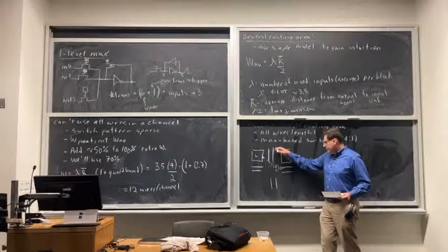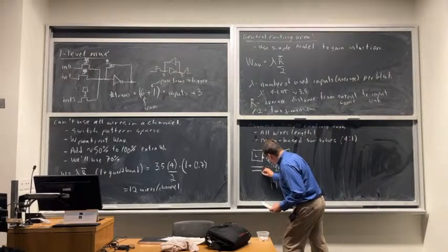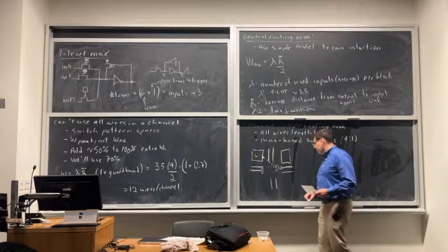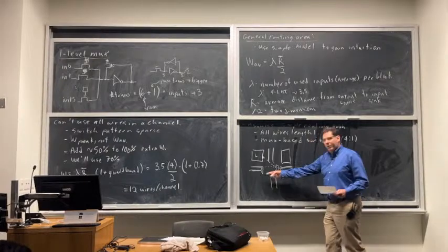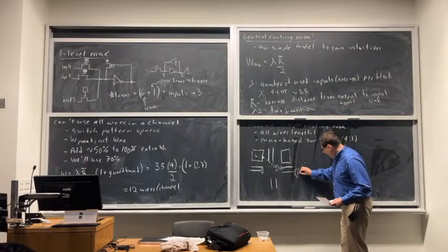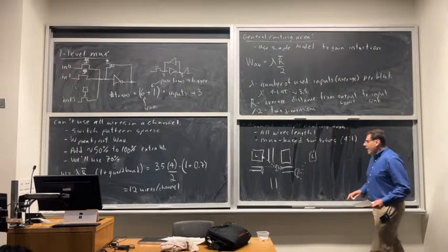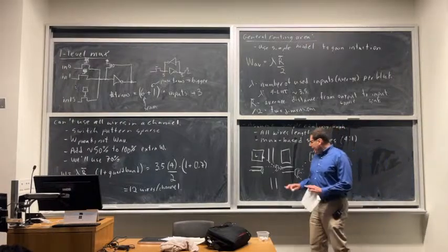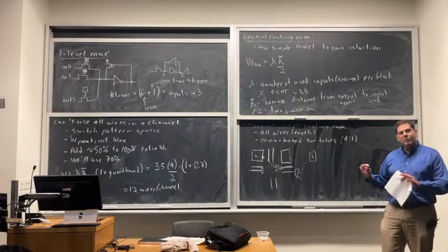We can go in each direction. So this wire is going to the right. It could be continuing a route that came from its left or above or below. This wire, we'd make the mux go the other way. This wire, the mux would be letting you go the other way. So its inputs would be coming from this side and from a different logic block over here. And if I repeat this, this is basically a routable routing architecture.